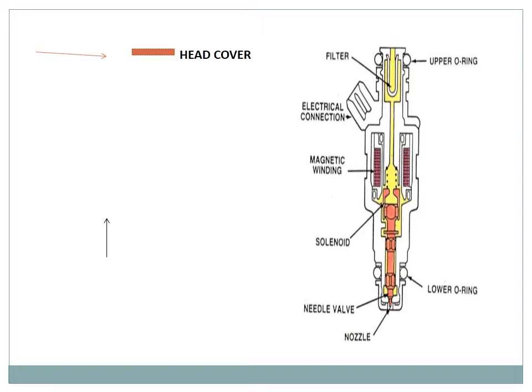Usually a fuel injector has a solenoid that is activated when the fuel is intended to be delivered to the engine, causing the plunger to be pulled toward the solenoid by magnetic force. This uncovers the valve opening, allowing the fuel to flow into the atomizer and out of the spray tip as it is under pressure. A valve spring is attached to the plunger to return it to its original position when the solenoid is switched off. Injection of fuel is achieved by the location of the cam on the camshaft.